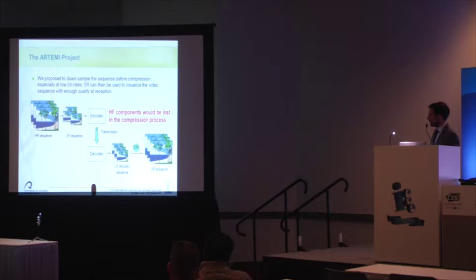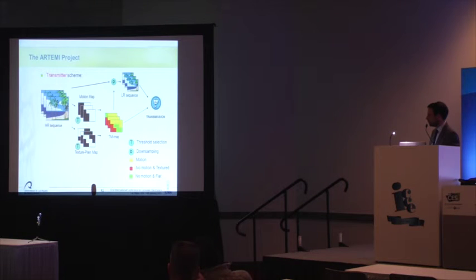But if we proceed like this, the high frequency components would be lost because we have a low pass filter in the encoder, and the SuperResolution will be useless because we won't have aliasing, we won't have high frequency components. So what we needed to do is just to get the required information for SuperResolution before transmitting, okay, before decoding.